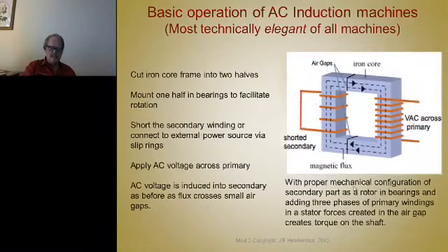Let's take that same transformer. Let's take a big hacksaw. Let's cut it in half. I didn't get these two cuts lined up, but they're supposed to be lined up. So we cut this in half, so we got a little air gap there. And now I've got the primary on this side, secondary on this side, and I short this secondary. This shows 4 turns there, but in a shorted secondary there's really only 1 turn, but consider these different bars all in parallel.